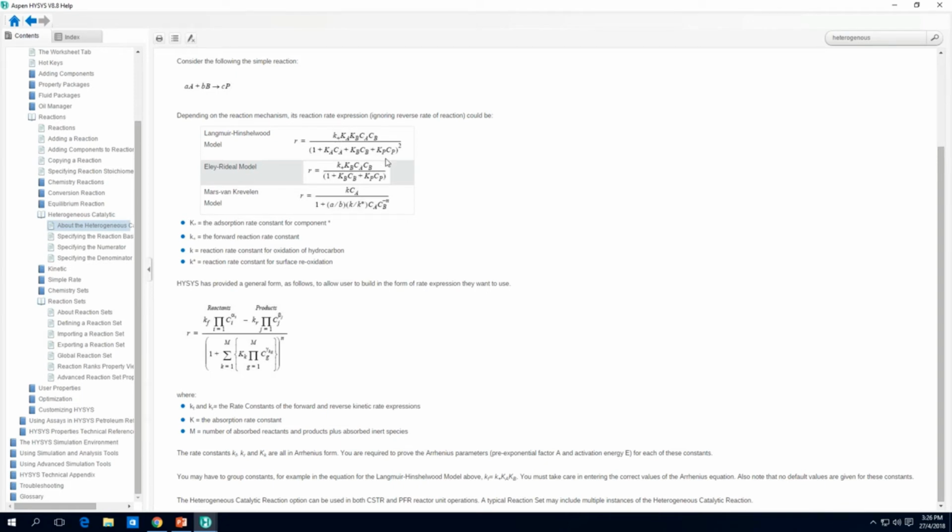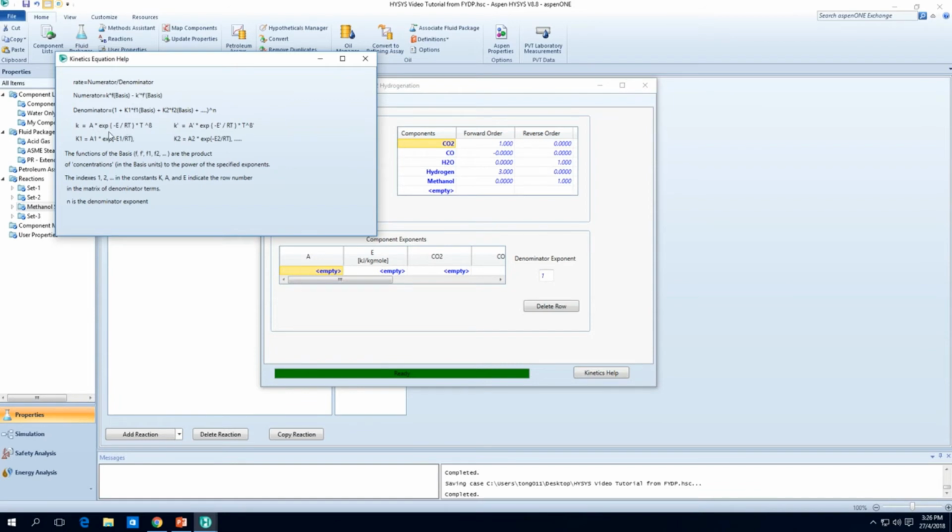Then you have to multiply the whole thing together, and it will be in some form of Arrhenius form, like so. HYSYS gives you a lot of freedom to choose and specify. So this is the pre-exponential factor, the exponential of minus E by RT, and so that's the K. And then there's this T to the power of some beta. Some models actually use that, but if not, beta will be 0. Then you'll just have A exponential of minus E by RT. Same goes for the backward rate, which is this K prime over here, the net backward rate.